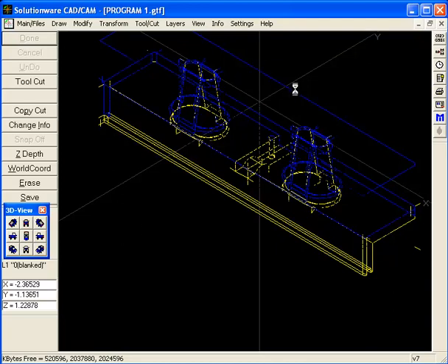You can see up here this boundary is our 2D cut, and it's being projected down on the surfaces. So remember, our tool is running a pocket back and forth up there just with no Z depth at all. Well, excuse me, it does have a Z depth, but it's from our smashed boundary, our Z smash boundary. And then it's going to run down, and as it hits every surface, it will stay off these surfaces. So when this toolpath is finished calculating, we'll take a look at it.